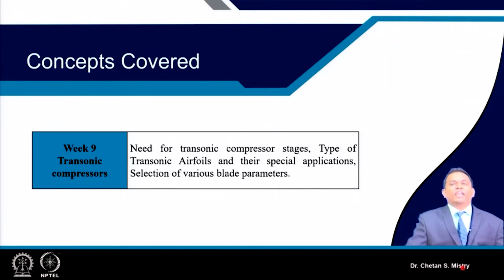It is even taking care of wider operating range, and such a high pressure ratio is possible by implementing transonic cases. What we realize is that in order to have high pressure rise, we need to rotate our rotor at very high speed, or maybe we need to change the diameter and other parameters. That is what we have explored.